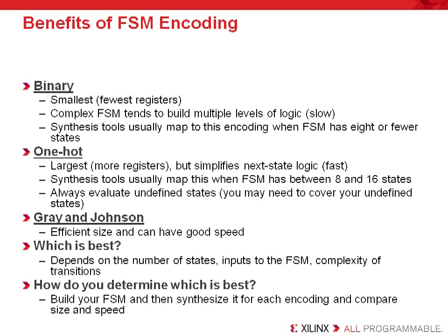So they would call the hotline, explain the issue, and the application engineer would fix the problem by convincing the customer to go to one-hot encoding. One-hot encoding worked most often because only 2 bits switch at one time, while binary encoding can allow many bits to change at each time. Well, now that everyone designs synchronously, there are no benefits to using one-hot encoding for reliability anyway.